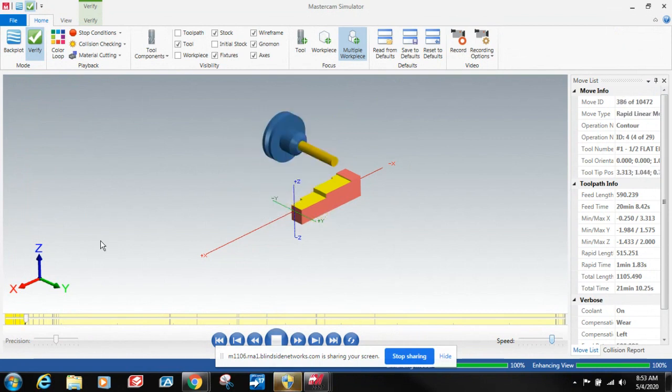Yeah, that's the difference in the simulation. Mastercam rotates the tool around the part. In reality, we rotate the part. So we can't run the spindle from the bottom of the part, but Mastercam can. I was looking at the practical part and thought, what is this geometry? I thought the spindle was at the bottom of the part. See, it almost fooled me. So in reality, the part would have rotated 180 degrees so that the spindle's still on the top. Oh, okay.